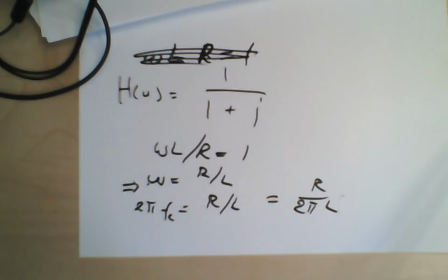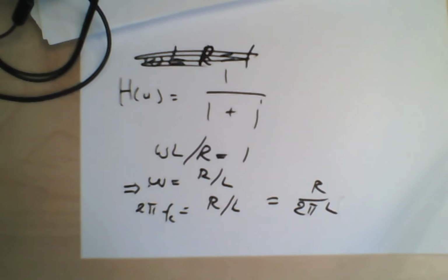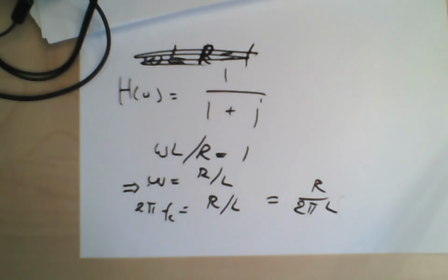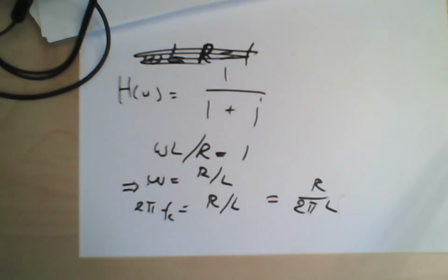No wonder it looked funny yesterday when you and I actually went through this material. Okay, high pass filter, similar, but you just switch the L and R. Okay, math is still the same, cutoff frequency, corner frequency, which is still wrong here. Sorry about that. But anyways, that's all there is for first degree RC and RL filters.